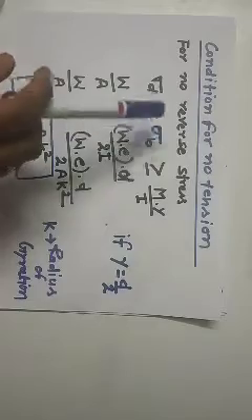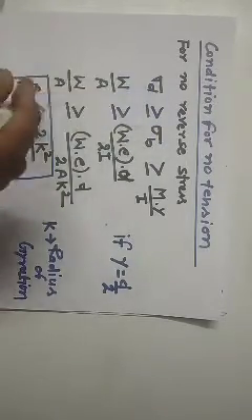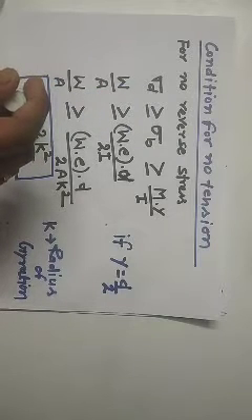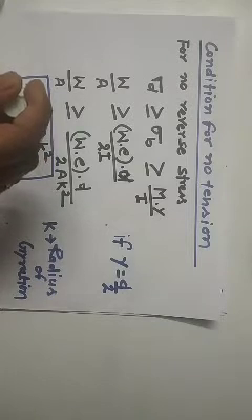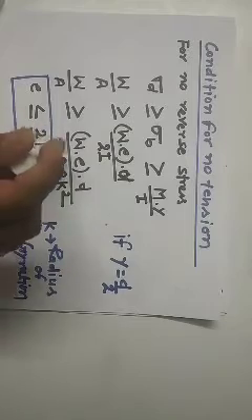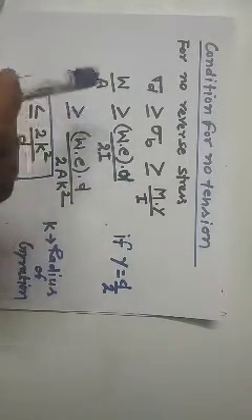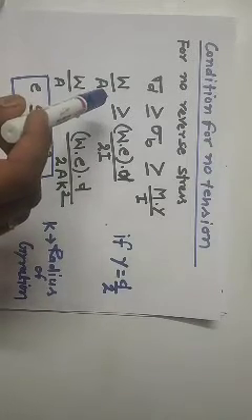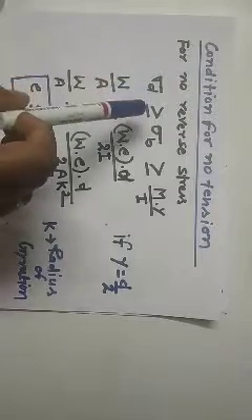The objective of this analysis is to make a calculation for a limit of eccentricity, that is E. Clear? Because the value of E will give you a zone in which, if we apply compressive stresses, there will be no tension across the section, and outside this zone, when we apply compressive stresses, there will be the chance that tensile stresses will be generated in the section. So in the previous lecture we